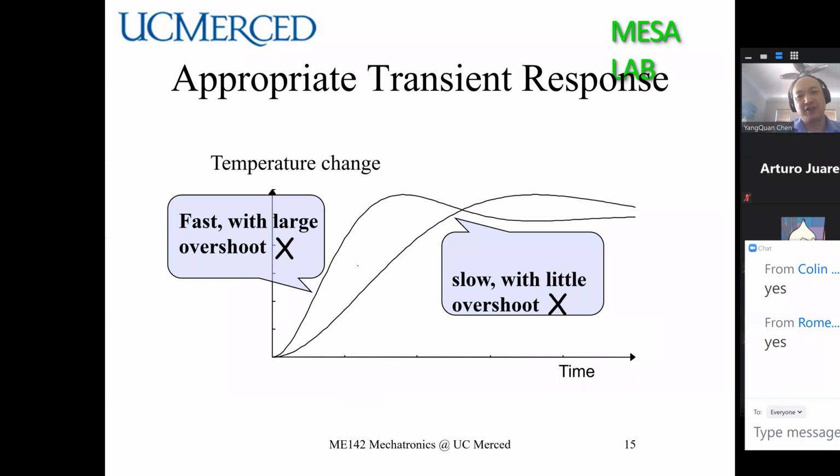So this is a visual illustration of what we mean by transient. The transient can be slow or can be large. When you have a slow transient, a smaller overshoot, then it's a slow response. If you want it a little bit faster, yes, you can, but probably at a price like this. This is a higher overshoot. But if you want a sluggish one, you can do it very slow like this. Make sense? So there's a trade-off depending on what you really want.